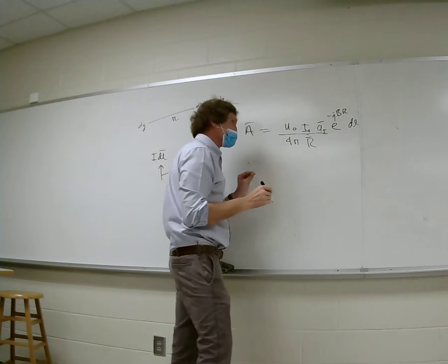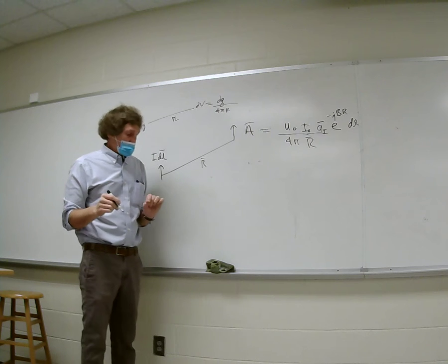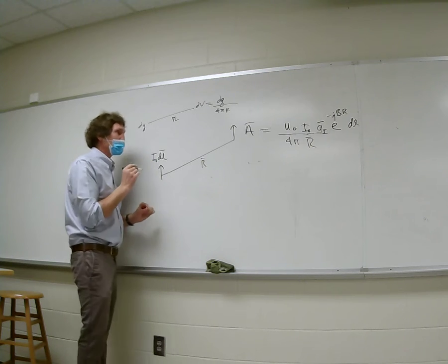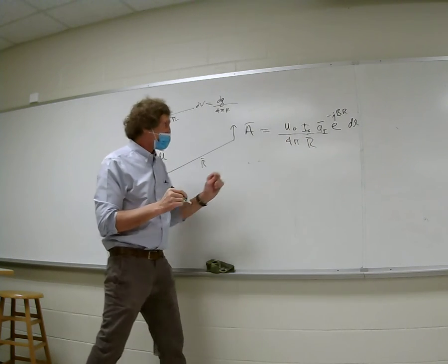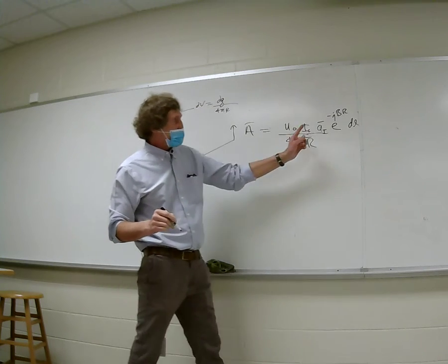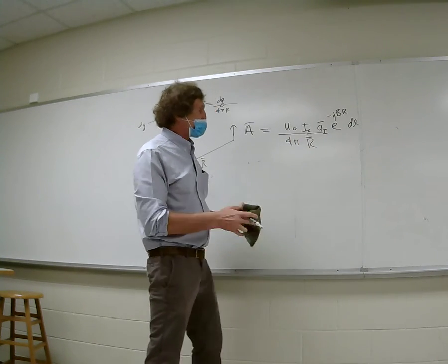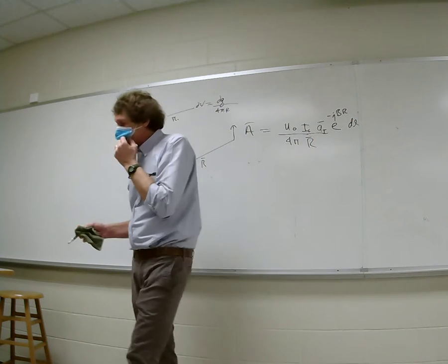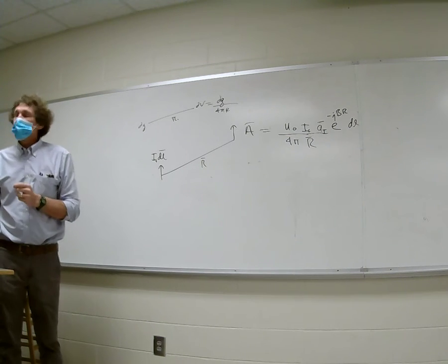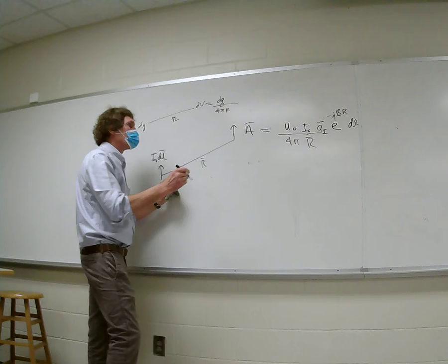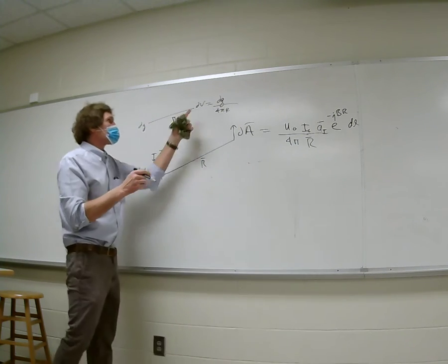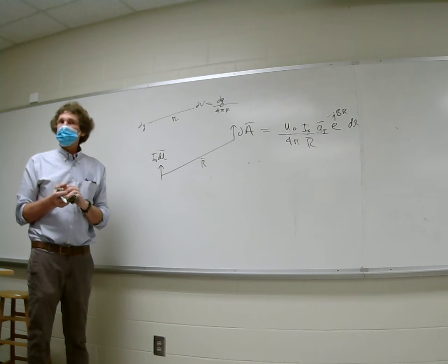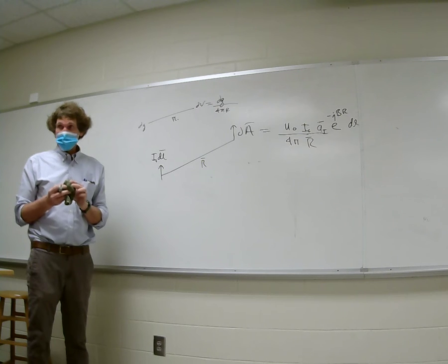Now I'm going to explain some things about this. Sometimes in the book, once you write that down, remember, I can call this line out. The only thing this is, the magnitude is here. The vector direction dl I broke up into ai dl, where dl would be a scalar. In his book, he'll have dl with a vector sense and just cover that up. But it's got to have a vector sense and a differential length, okay? Now that's the differential electric field, so I didn't put this there, but this would actually be dA, just like that would be dV. The A there is called the magnetic vector potential. You're going to see in a minute this sort of goes away after I take care of a few things.